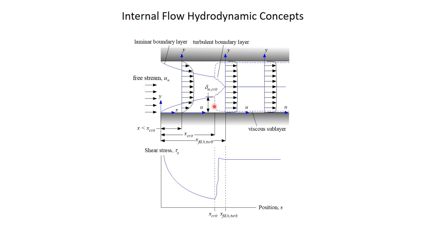Once the turbulent flow happens, right, you would expect the velocity distribution to change quite a lot. So here's a developing laminar flow, right? We have this nice gradual velocity gradient that goes from the core to the wall, right? When I transition to a turbulent flow, I expect to get back to that situation where I have a viscous sublayer very close to the wall, and that's where most of the velocity gradient happens. And then the core is actually a relatively uniform turbulent core, right? The velocity in here, at least the average velocity, is fairly uniform.